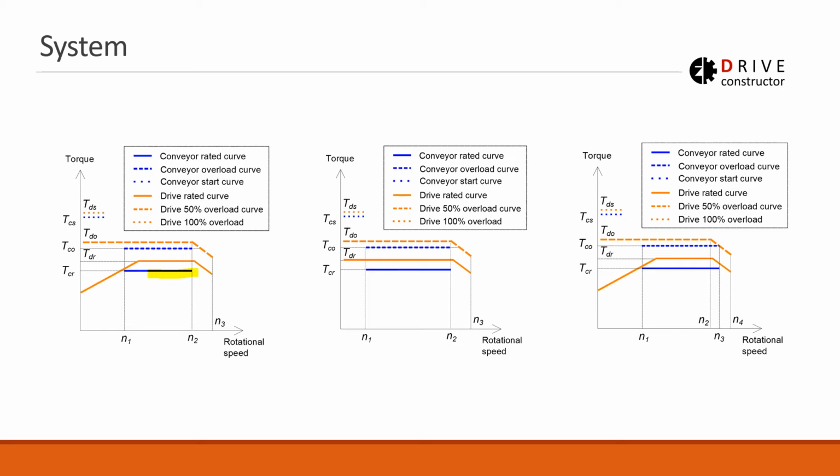What the slide is also showing us is that there can be not just the main torque, but also some overloads. The conveyor can suddenly be overloaded because there is a big stone on it or something like that. If it is the mining industry, it can be stuck because something is stuck on the belt of the conveyor and so on. So it may have different sorts of overloads, and overloads will vary in amplitude and duration.